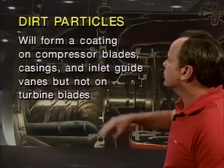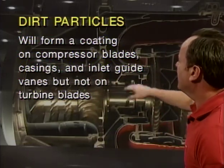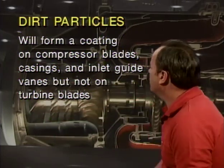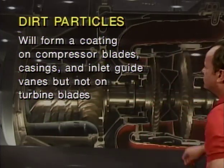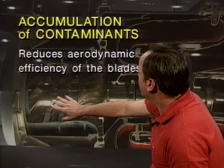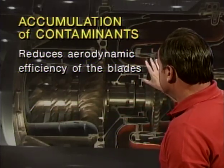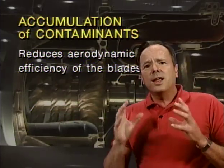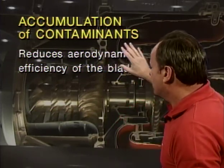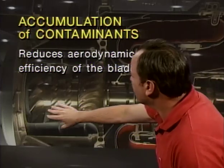So dirt particles will form a coating on compressor blades and the casings and inlet guide vanes and the cool section of the engine. But when you get back here in the hot section of the engine, you're not likely to get a coating because you're likely to burn it off. Now, when you do have an accumulation of contaminants in the compressor of a turbojet engine, it does reduce the aerodynamic efficiency of the blades. And what that really means is for any given thrust or EPR, you're going to have higher EGT. So accumulation of contaminants is a very, very bad thing. You want to get rid of those contaminants.